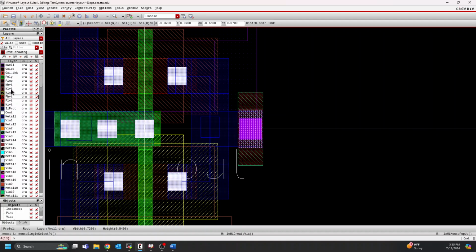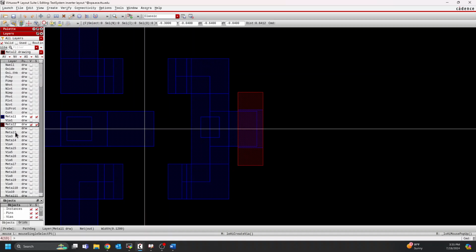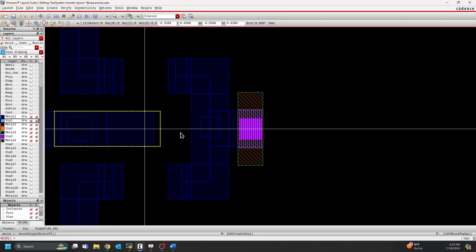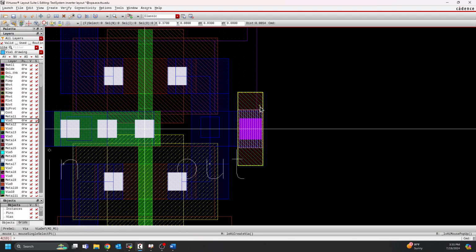We have a metal 1 layer here. So this is our metal 1 via, this little rectangle here on the end. We have a metal 2 portion, a metal 3 portion, and a metal 4 portion here. So this is actually going all the way up from metal 1 to metal 4. And if you need to have something routed on metal 4, for example, this is a really good way that you can do that. So you can use the stack up tool in order to create that.